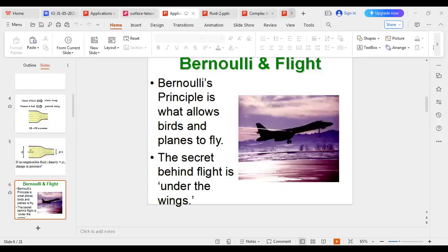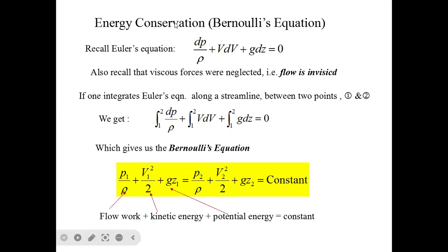So this is the application of Bernoulli. For energy conservation, the Bernoulli equation can also be written. Recall the Euler equation, dp by rho plus v dv plus g dz equals 0. Also recall that body forces are neglected and the flow is inviscid.